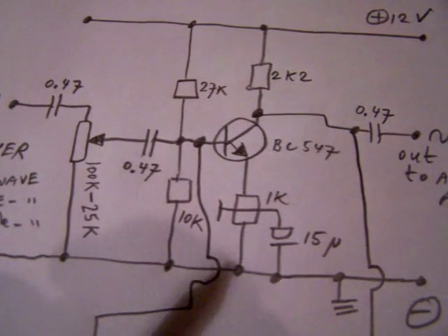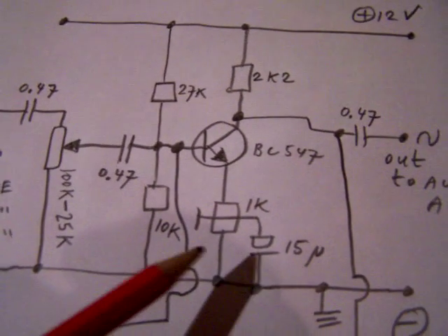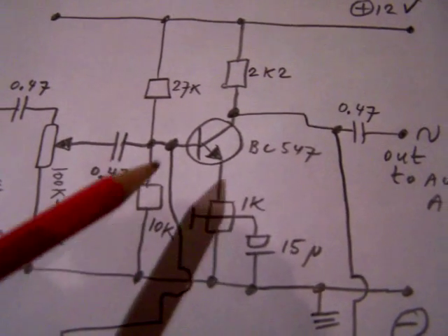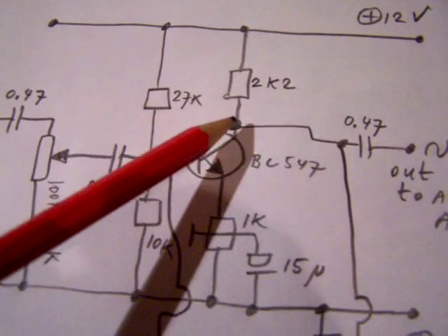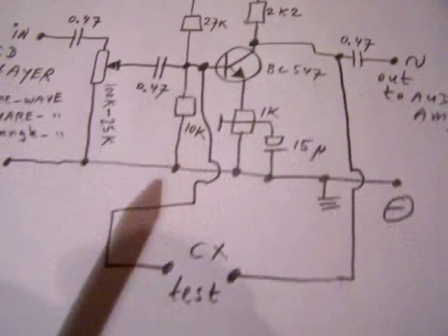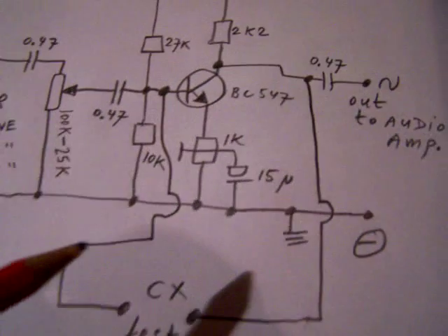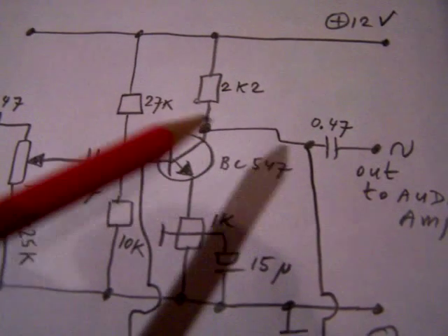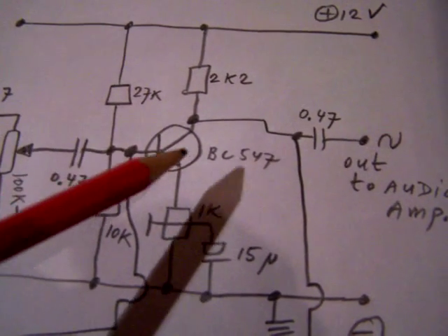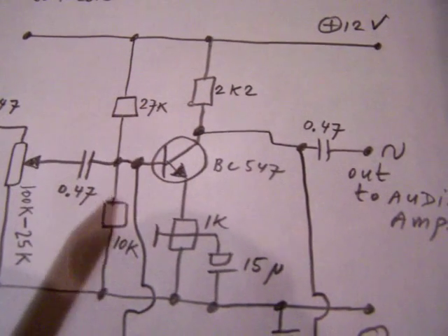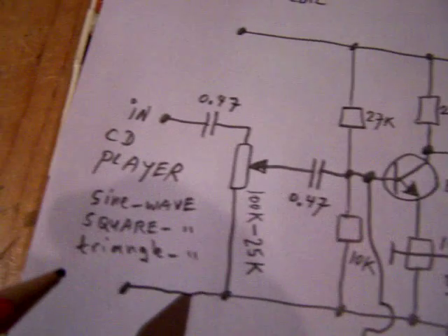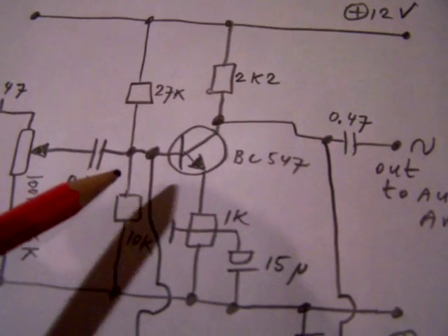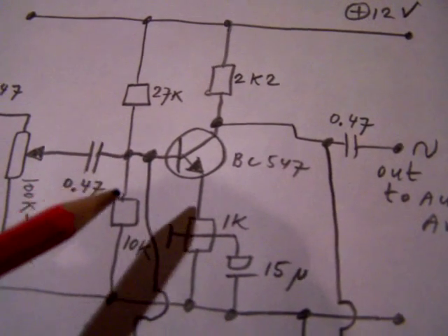This is a one-stage transistor amplifier. With this resistor we can set the amplification, and I connected a capacitor between the output and the input, and that means that we make the transistor stage frequency dependent, and in this case all high frequencies are cut off. So I want to study now whether the high cutoff, the sound, differs with different types of capacitors.